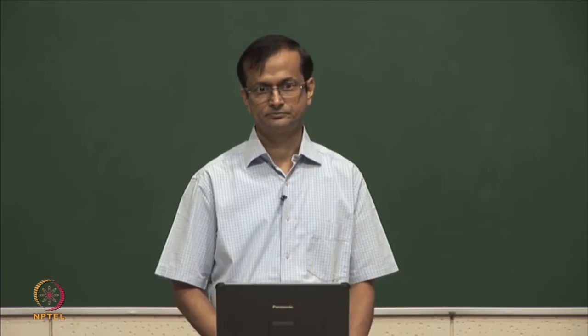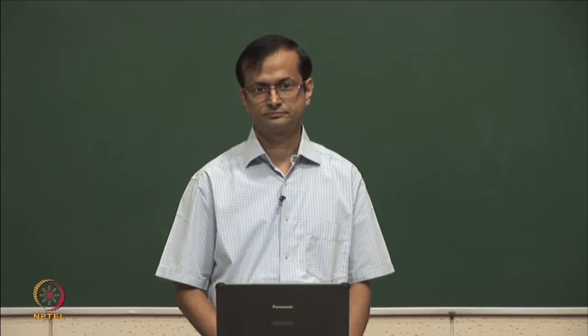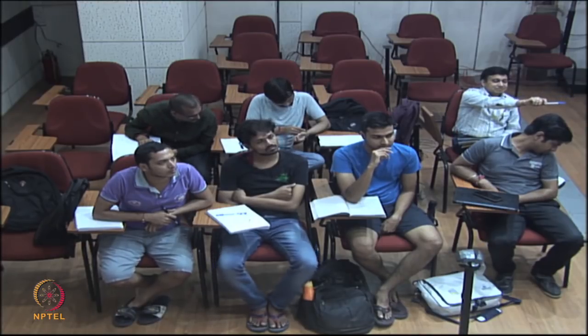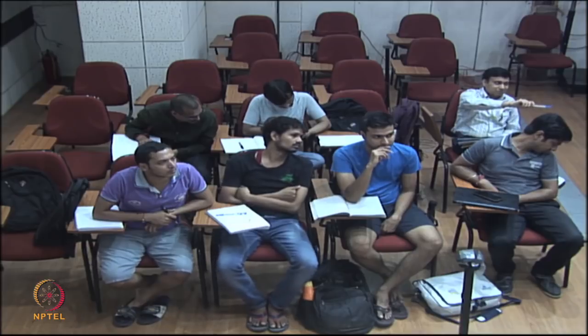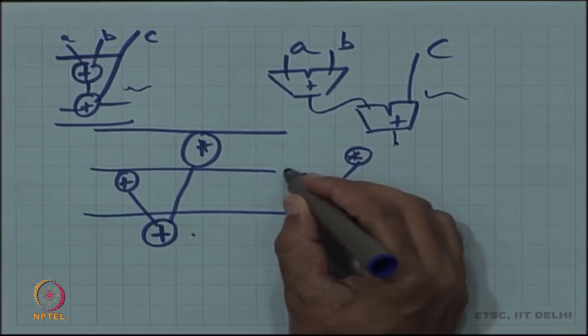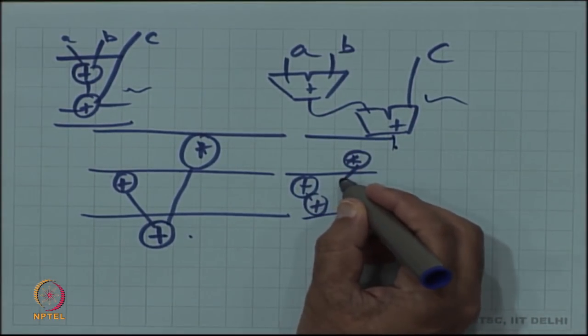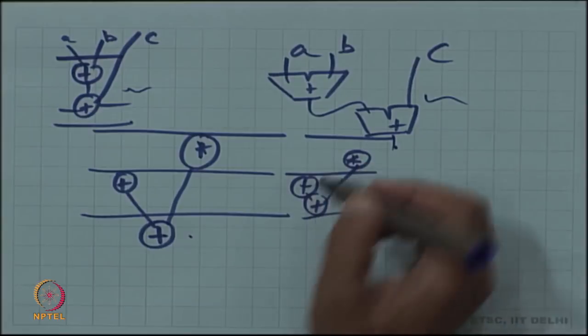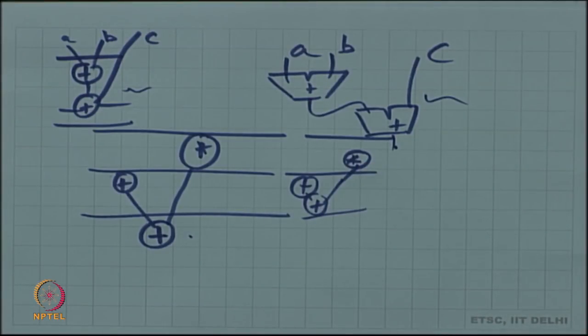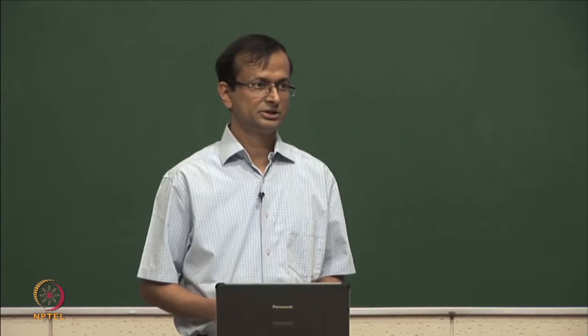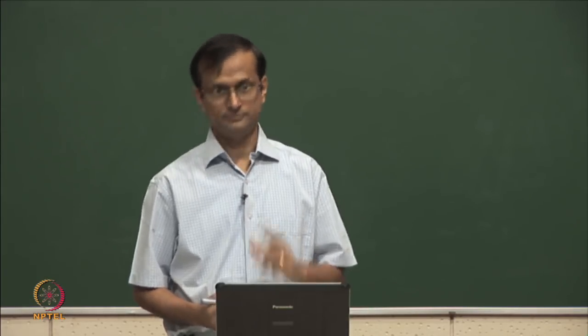In this case, what will happen is we'll go back in time and then add the second add operation there, right? Yes. So we are altering our scheduling so far. We are not looking back at previous cycles, but now in this case we'll go back to a previous cycle and then create. So let us tweak, since we are violating something, what it is that we were not supposed to violate. We will not revisit the scheduling decisions for a node.